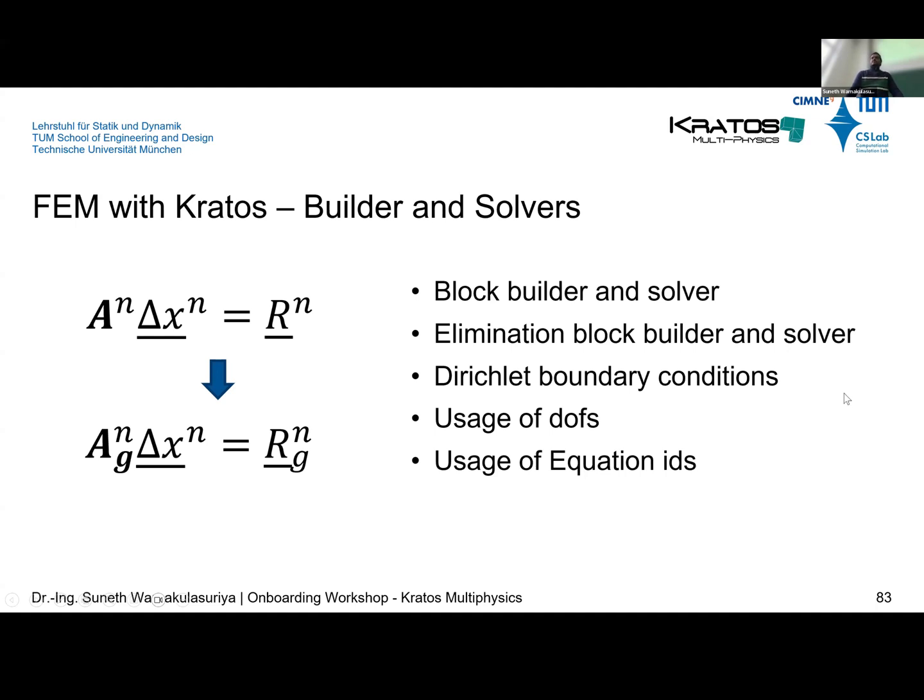Remember Neumann and Robin boundary conditions coming from the conditions, which I told you, elements and conditions. It's just a local matrix contribution going into the global matrix contribution. So if you are developing, let's say, a wall law for fluids or a heat flux law for convection-diffusion, then you have to develop your own condition, which gives a local system matrix. Then it is contributed to the global one. That's how you get that wall law into the system matrix for your solution.